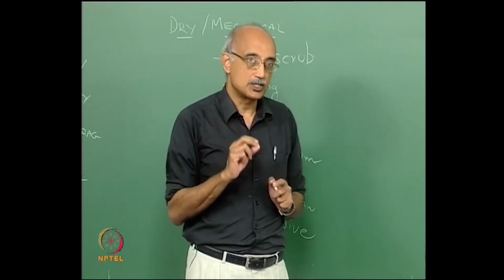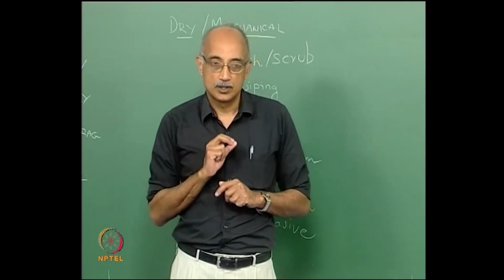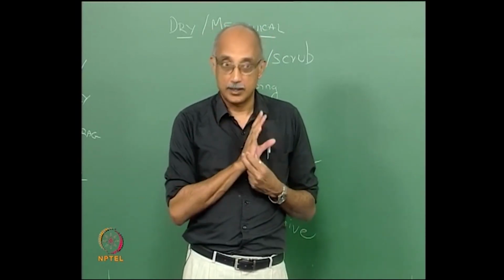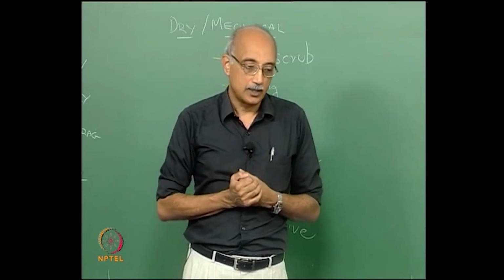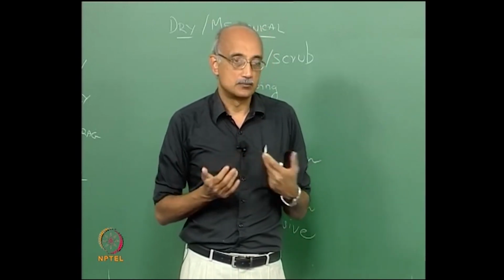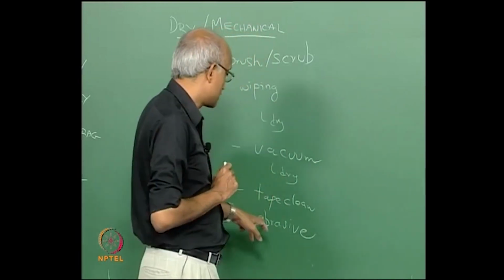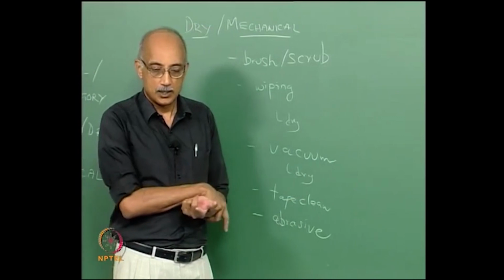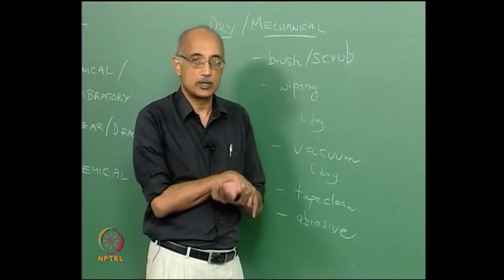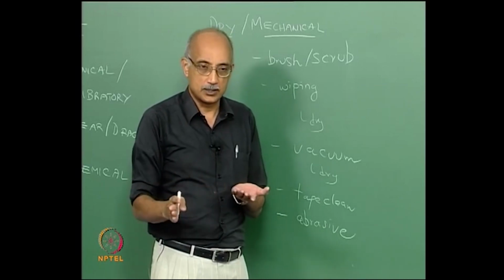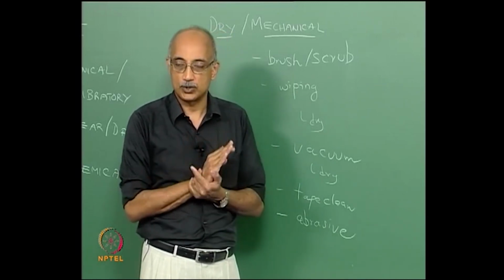But here again, the potential for doing damage is quite high if you are not controlling the kinetic energy of the impacting material and its direction. You can quite easily cause unanticipated damage to the substrate you are cleaning. But for processes like deburring, even paint removal, frequently you have applications where you have to remove paint from a surface and then reapply a surface coating.